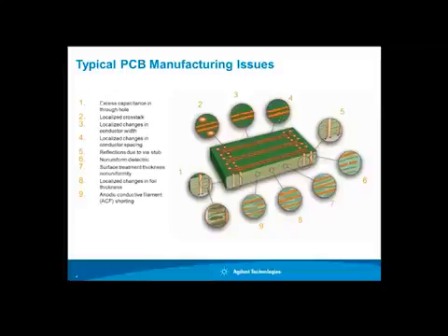In number 4, you can see we have localized changes in the conductor spacing. Simple solder splash on one trace and not the other will create this type of impedance mismatch. Number 5, we have reflections due to via stubs. Anyone who's designed backplanes can attest to this problem. And you can avoid that by doing back drilling or using micro vias, things of that nature. 6, we can have non-uniform dielectric material. Anytime that dielectric is non-homogeneous, it's going to cause problems in impedance.